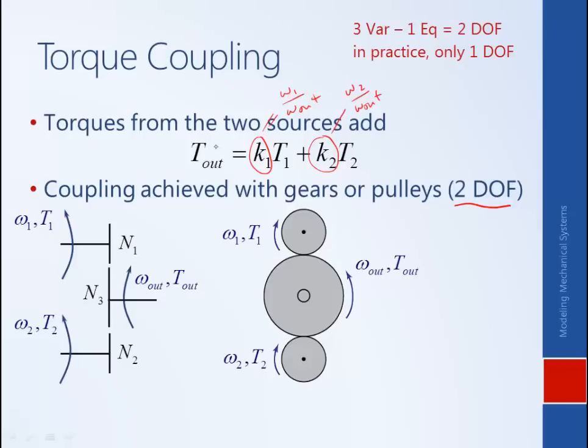And so T out is chosen by the driver. Therefore, we can choose the IC engine torque to be whatever we want, but then in order to get the output requested by the driver, that completely determines what the torque generated by the electric motor must be. So we can define one of the 2, but then the other one will be constrained by what the driver's requesting.